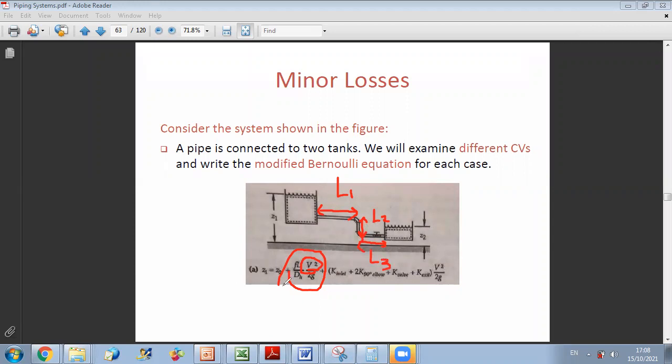And in order to get the friction factor, we should do what we did already together before. We should go to Moody chart, or we should go to other charts depending on the case. So we should find Reynolds number, function of the unknowns that we have. We should find the expression of Reynolds, the expression of epsilon over D.